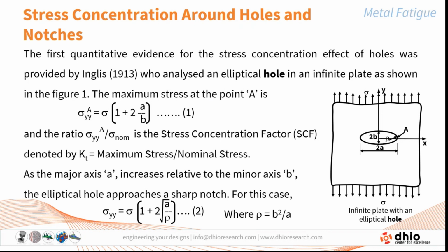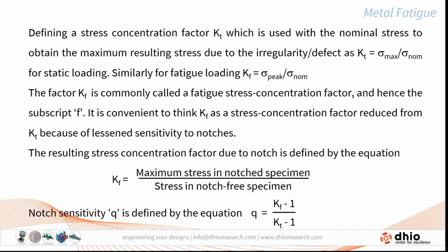So the notch effect is going to be very critical. As we know, the stress concentration is what is considered in static design, whereas when the loads are cyclic, we have to look into the stress concentration factor due to fatigue. In static analysis, the stress concentration is defined as the ratio of the maximum stress to the nominal stress.